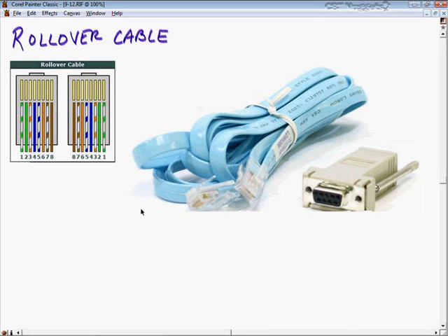And you can see with the rollover cable here, this just shows you that this is basically all the cables and the pins are rolling over from one side to the other. So everything kind of gets flipped over when it gets to the other side of the connection.